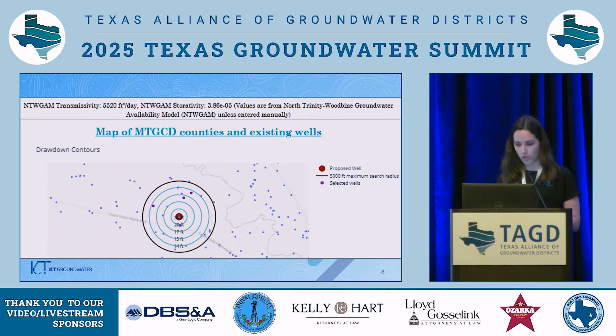This is what the tool will generate. You can instantly see how the groundwater might react to that proposed well, and it allows you to see many different scenarios. At the top, the transmissivity and storativity values from the GAM that were pulled for this particular proposed well scenario are displayed. And the contours here are generated for 1 year of drawdown. A maximum search radius is generated, and any wells within that search radius that are within the proposed aquifer are highlighted for you.